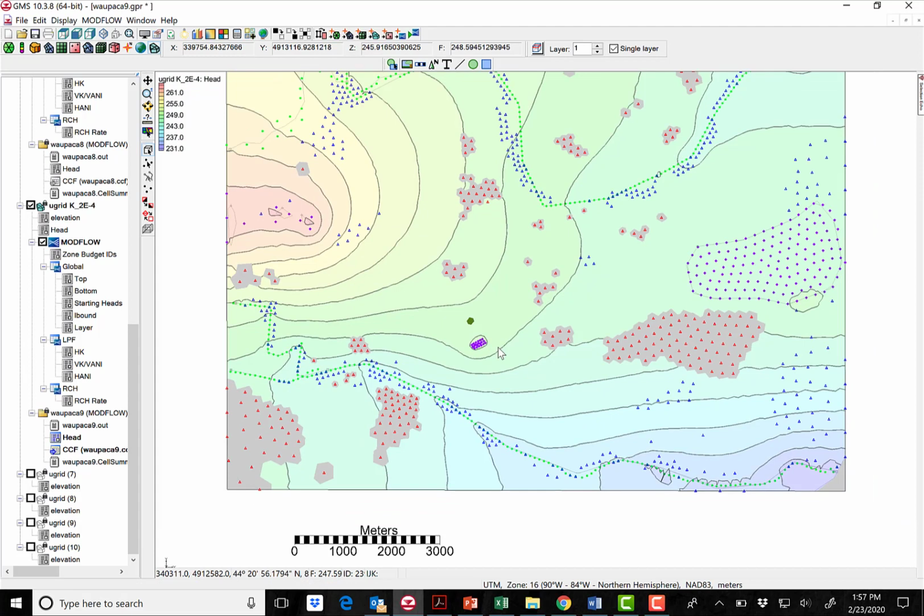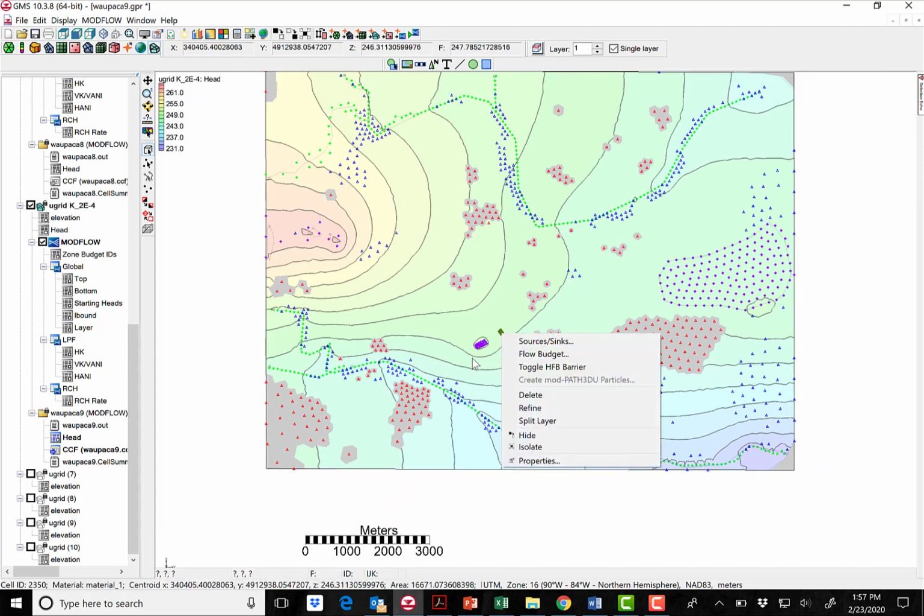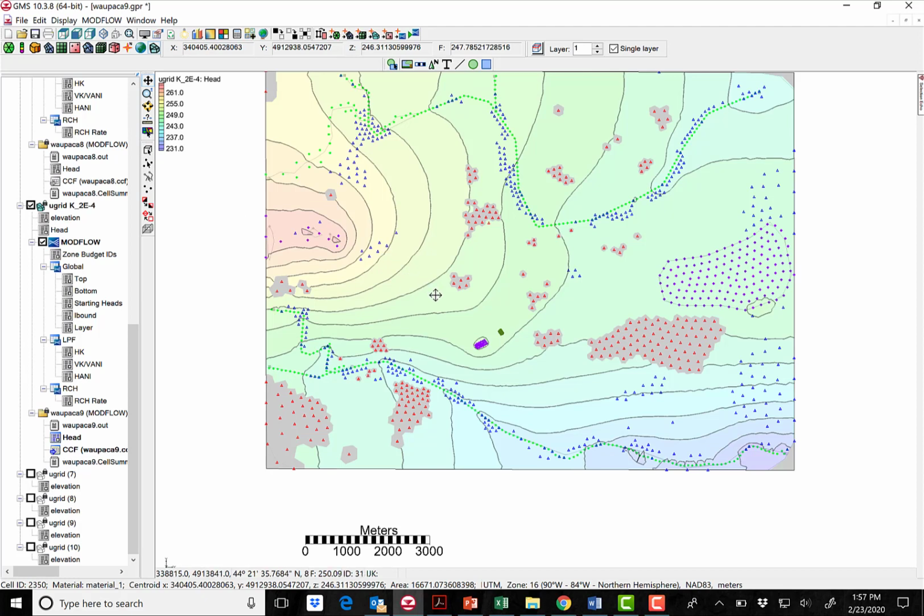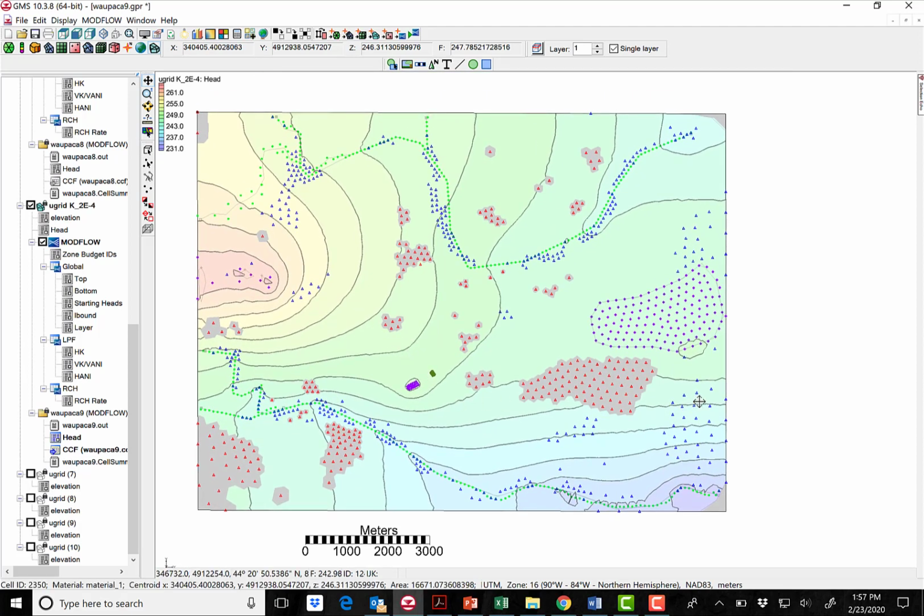So in general, I think we've got a model here that's a pretty good starting point for calibration using site data. Keep in mind that what we've done so far is really just get the topography from the DEM and get recharge from a regional assessment. The recharge was actually based on stream flow, so it may be a little bit low, but this provides a simple way to get started with a groundwater model that would be a starting point for further refinement once we can get access to field data.